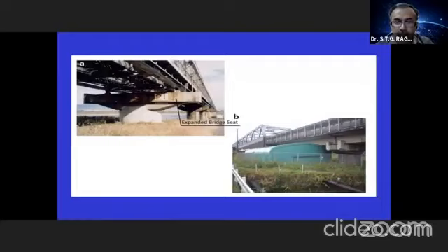And now this is one bridge which is crossing the fault itself in Japan. They have provided an expanded bridge seat here, so that whenever there is a shift, they can shift the track or the girder. And you can see this box here. It is provided so that all the repair equipment is here. If there are any issues, they can quickly repair things and get the railway working. This is, I think, a bullet train track.